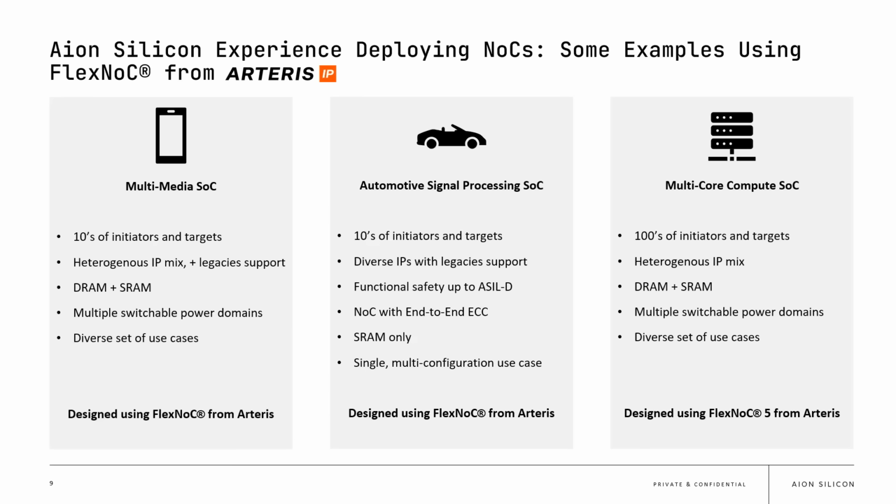So at AION Silicon, we've deployed a number of SoCs using FlexNoC technology from Arteris, and here are some recent examples. To give you an idea of the complexity, I've stated the number of initiators and targets. We've got the multimedia SoC, which is in the tens of initiators and targets, and similar for the automotive SoC.